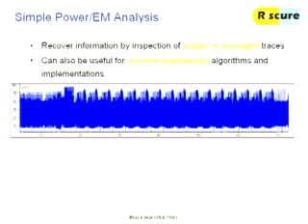So what can we do with it? What can we do with traces, the measurements that we've taken? A trace is a word for a measurement for us. The first thing you can do is start reverse engineering the information. If you see something like this and you see the rounds, it tells you something. But also, if you did the same thing for the boot process, for instance, you could maybe see what's happening in the boot process. Maybe you can identify where it's going over the memory. Maybe you can identify where it's making a signature, or a decision on a signature, stuff like that.